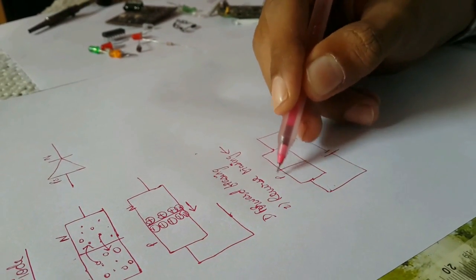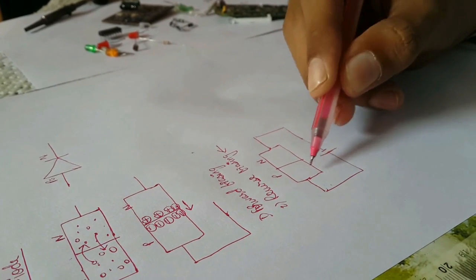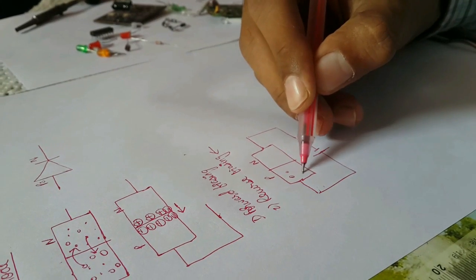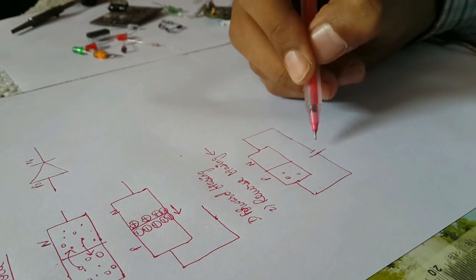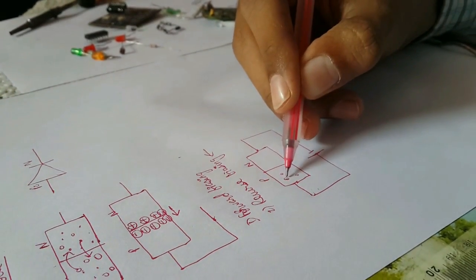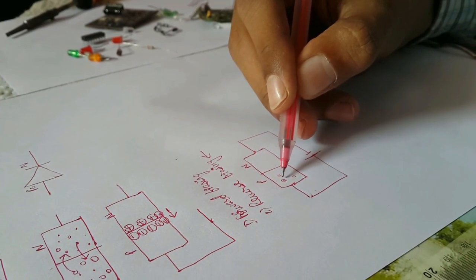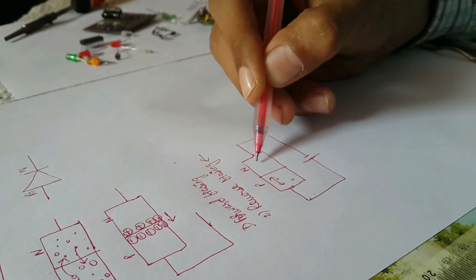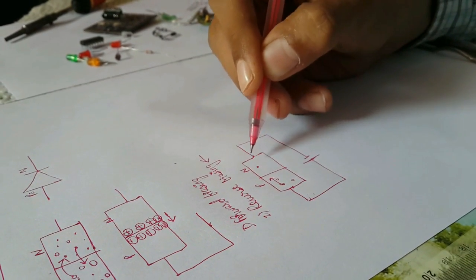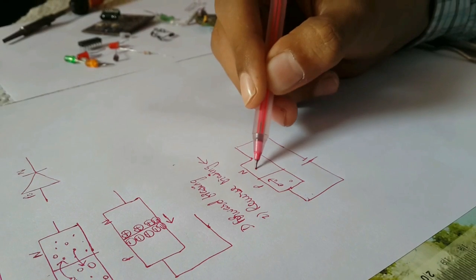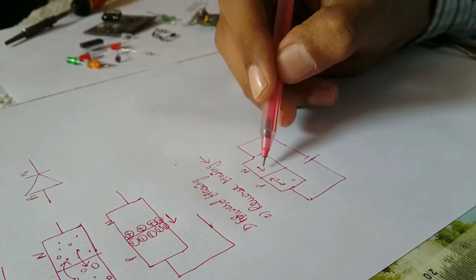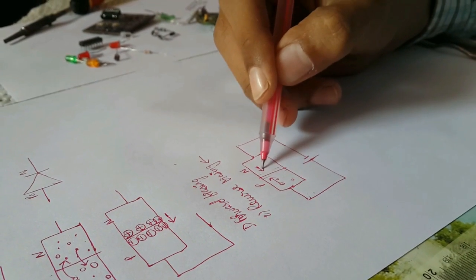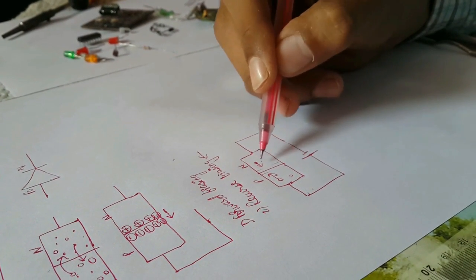When the diode is in forward bias, the positive is connected to the P type of the diode, then the holes here feel a force of repulsion. Since this is positive and these particles are assumed to be positively charged, they get a force of repulsion over here, and at the negative terminal the electrons also get a force of repulsion, and there will be no more junction over here and current will flow along the diode.